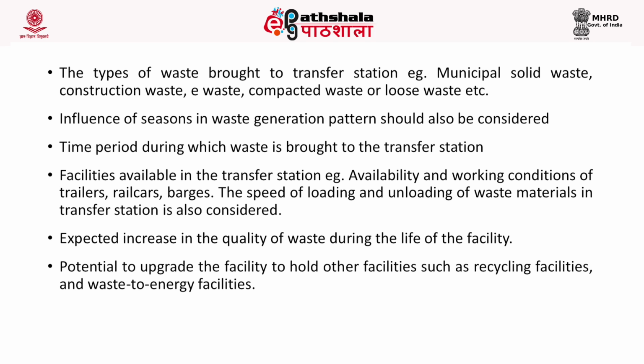Also, the speed of loading and unloading of waste materials should be considered. Expected increase in the quality of waste also should be taken care during the life of the facility. The potentiality to upgrade the facility to hold other facilities such as the recycling facility and the waste to energy facility should also be considered, determining the size of the transfer station.